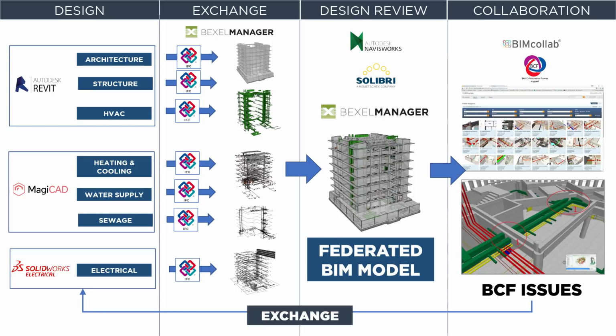To achieve something like this, the project manager will use the BIM Collab format, or BCF, another file format developed by buildingSMART that is suited to track the issues as they're being identified, reported on, and resolved in the course of the BIM process. It allows sending model markups, clash reports, general comments between all project members, and so on. When the issue is solved in the modeling software, the BCF is updated, and this is communicated back to the project manager. Similar to the IFC format, it's supported by most BIM software applications.